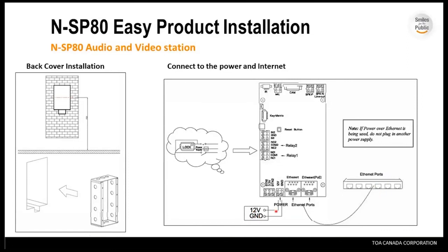And up here, we've got a speaker in, line out, external speaker, that type of thing. Microphone connection. Key things you'll probably use here are contacts, normally open, normally closed, relays for your door strikes and entry and that type of thing, directly from the master or from the substation. So that's a quick view of the back of the V or the audio substation.